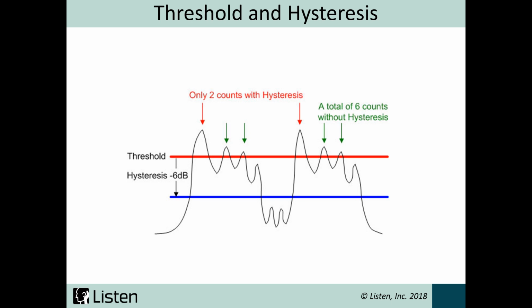And to avoid false peak detection, the hysteresis level should be set to a value greater than the background noise. As you can see, there's 6 points that cross over the threshold. But if we give a negative 6 dB hysteresis value, the loose particle algorithm will only give us back 2 failures. It ignores the peak over threshold until the sound level goes 6 dB below.